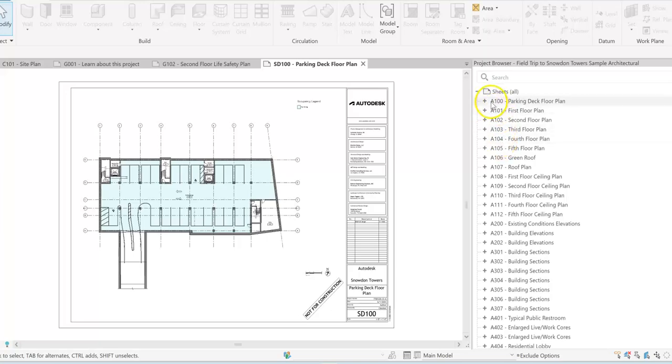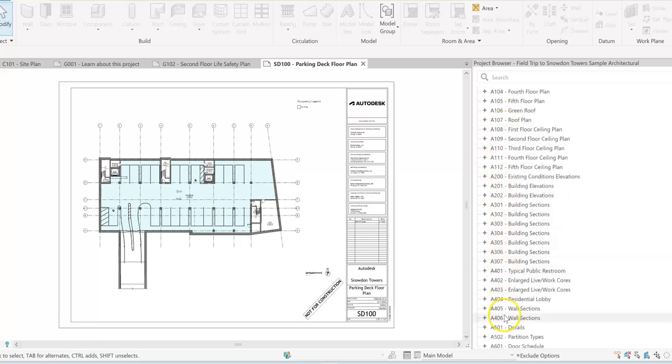A set of construction drawings for architectural. Typically, you can have A100 or you can just have A1, depending on the complexity of the project, personal preference. Smaller projects, you probably can just get away with A1. But something like this, more in depth, you can have many sheets that constitute the whole. But you can see that each time you jump up by 100, you're going to have a different type of topic. Those are always consistent.